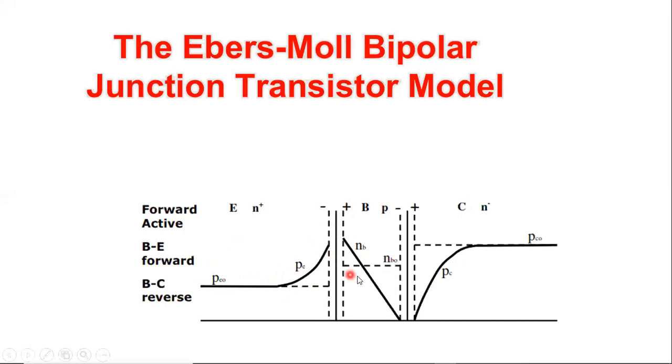As you can see here, this increase represents that this junction is forward, because a huge number of holes travel from the P side to the N side, so holes increase, and a huge number of electrons travel from the N side to the P side, so electrons increase. Now, what about this junction? In this junction, we have a reverse bias. What do we mean by reverse bias? More electrons as a minority will leave this P and go to the N because this is a reverse direction.